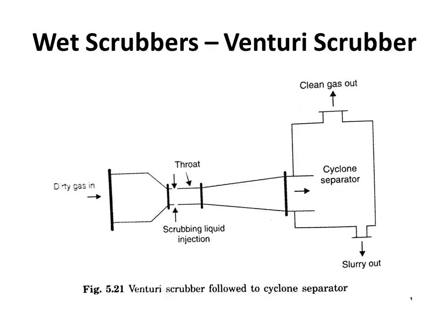Venturi scrubbers offer high performance collection of fine particles, usually smaller than 2 to 3 micrometers in diameter. They are particularly suitable when the particulate matter is sticky, flammable or highly corrosive. The high performance of the Venturi scrubber is achieved by accelerating the gas stream to very high velocity, that is 60 to 120 meters per second. The high speed action atomizes the feed liquid that is generally introduced in a uniform fashion across the throat through several low pressure spray nozzles directed radially inwards.